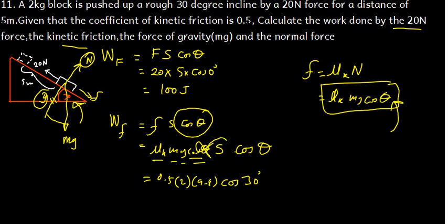What of the distance? The distance we've been told it slides. Where is the distance given? A distance of 5 meters is given there. So the distance is 5. And then cos theta. This theta is telling us the angle of the direction of the friction. Friction is going down, and this thing is sliding up. So that theta is telling us this angle, which is 180.